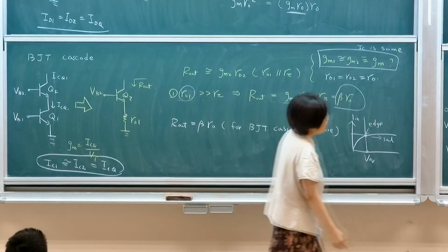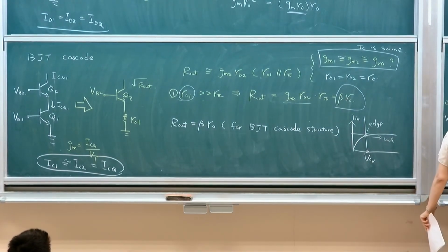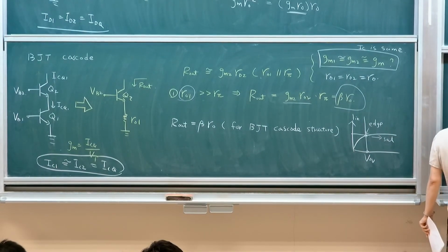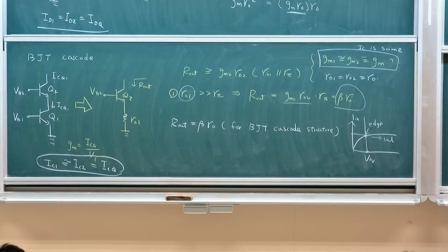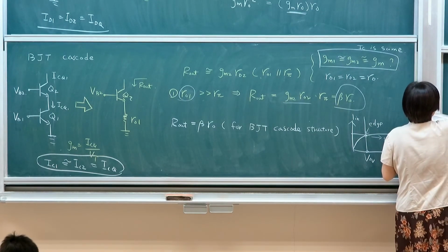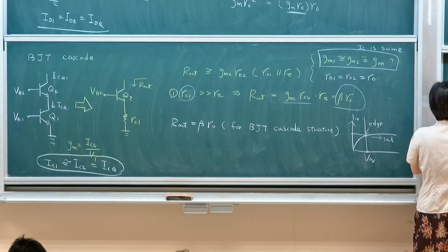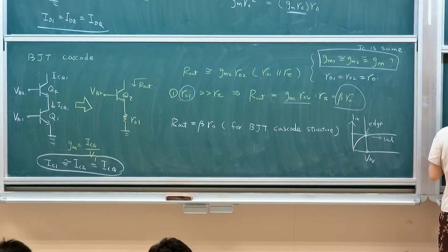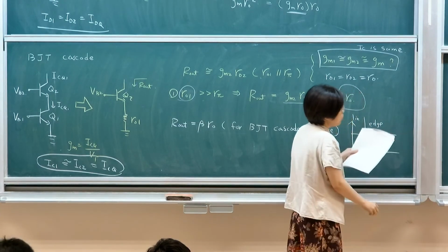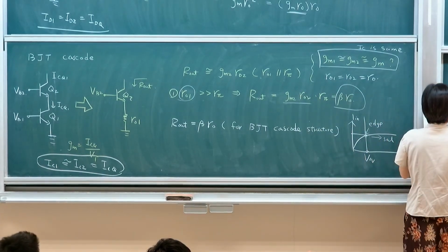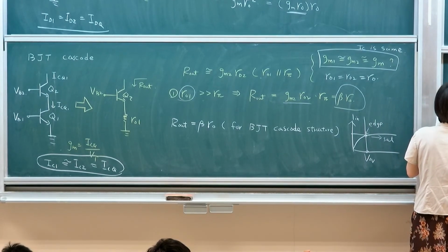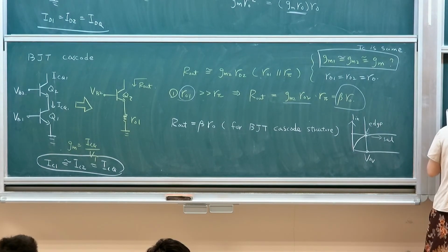So lastly, we need to find out its output resistance. We're going to follow its equation, which is fairly simple. For part B, Rout was simply gm2 RO2 times RO. So what we need to do is find, we already know gm is 0.5 milliamp per volt.